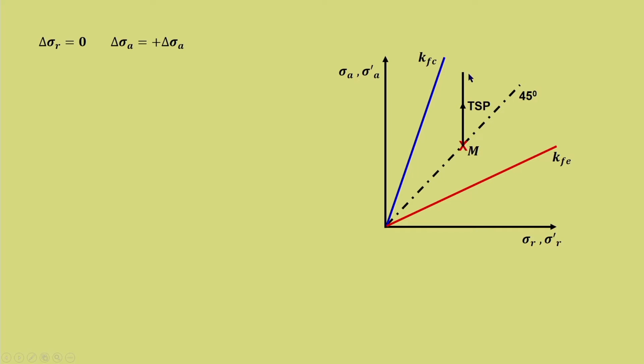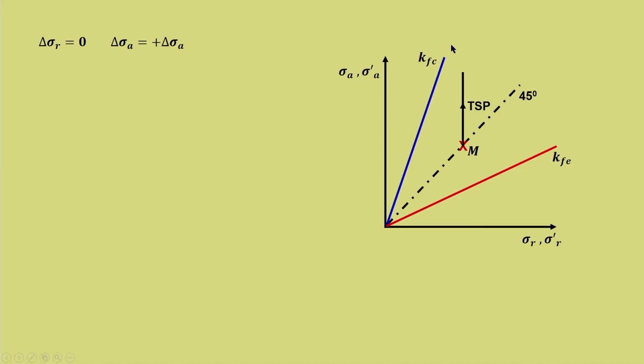In fact, when it comes to undrained testing, you will see that total stress path will not represent what it actually has to represent about failure. So, it is all governed by effective stress path. Whether it is complete or not, whether the total stress path is meeting or crossing the failure line, it hardly matters.